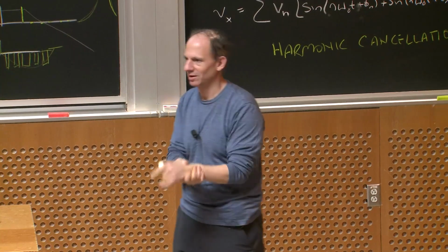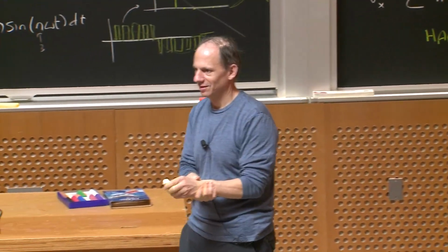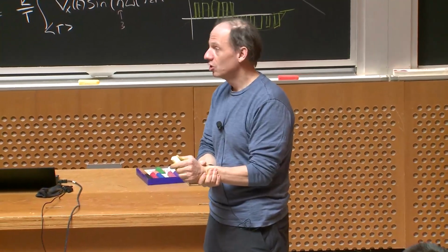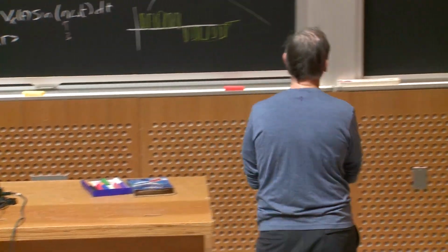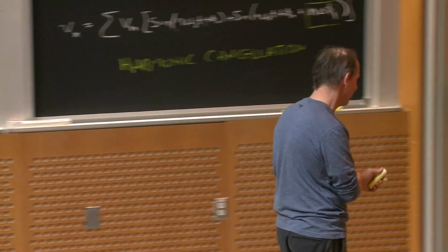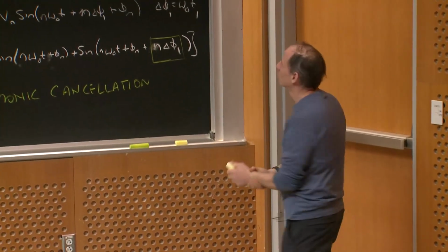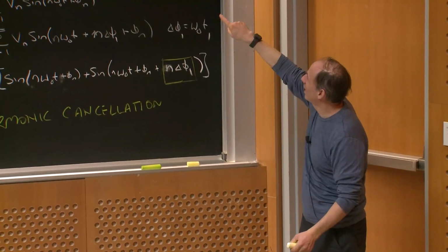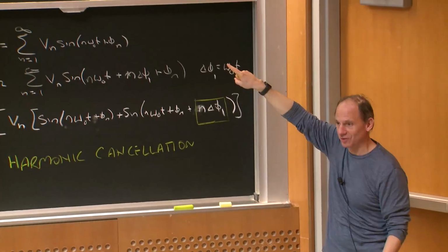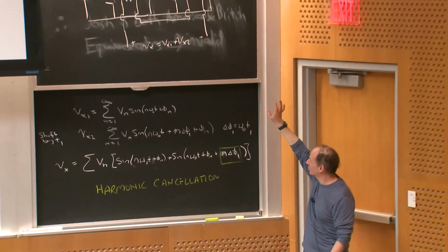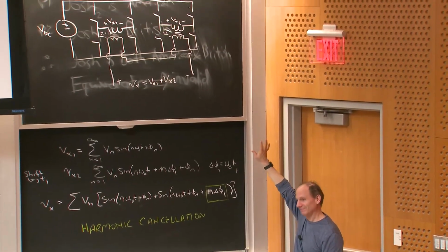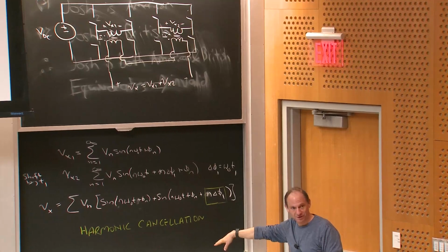Excellent question. Do you also use this trick to just increase the AC output voltage? You could, yeah. So what would be another benefit of this? Right, the output has twice the amplitude of VDC I could synthesize. And that's just for this particular implementation, which is only one way to do it.